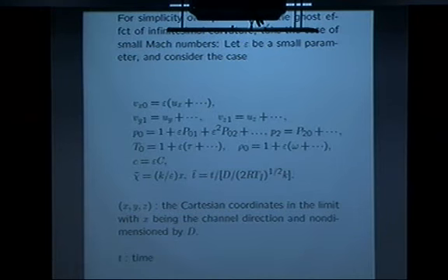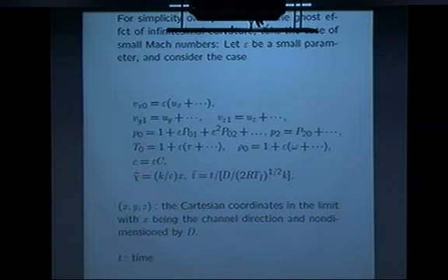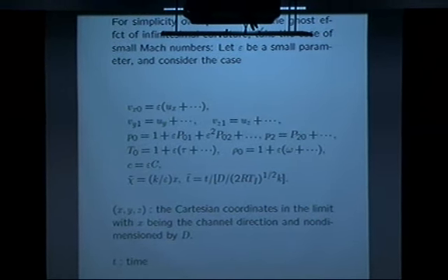This is a quantity of the order of the Knudsen number. They start at the leading order term. Pressure, the leading order term, is expanded in mean free path. The second subscript means this expansion. And this is the pressure of order Knudsen number squared. That starts this way, and likewise the temperature and the density. And this constant is scaled this way, for small mean free path.